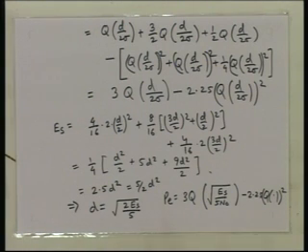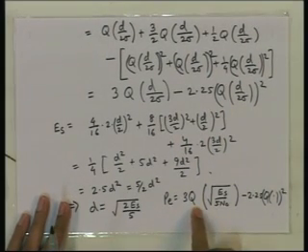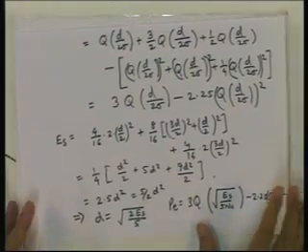Take a 16 QAM constellation, add white Gaussian noise in the channel, and do usual maximum likelihood detection, and find out what probability of error you get by simulating, by transmitting a large number of symbols, and then compare it with this value. This value can be computed in terms of the ERFC function that is available in MATLAB. So, one can verify this by simulation.